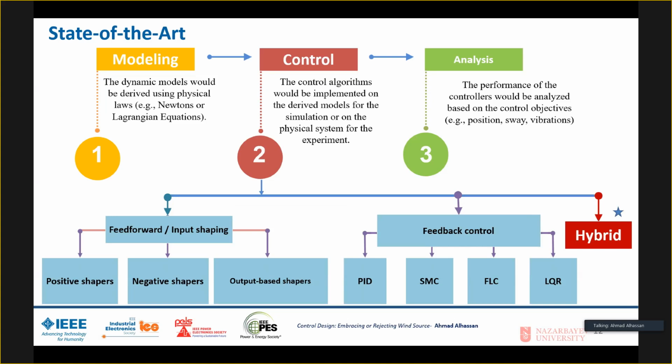There are many types of feedback and feed-forward controllers. As we can see, the most prominent one is the PID, but there are more advanced ones. And for the feed-forward, we have input shapers, which can be positive, negative, or output based.